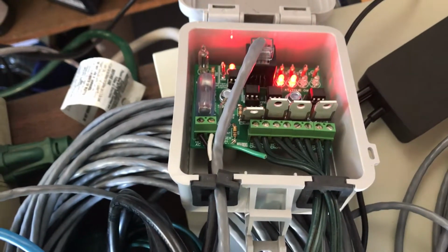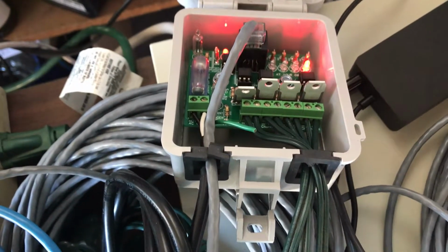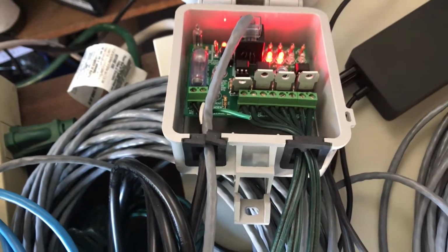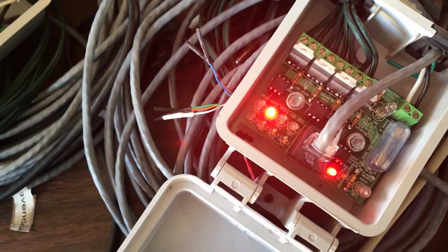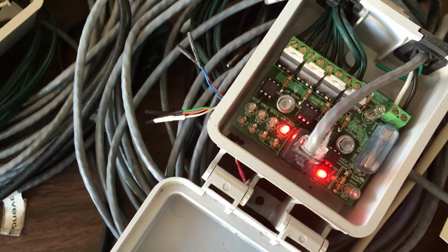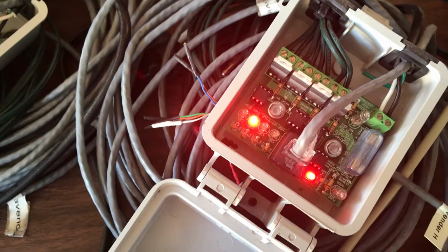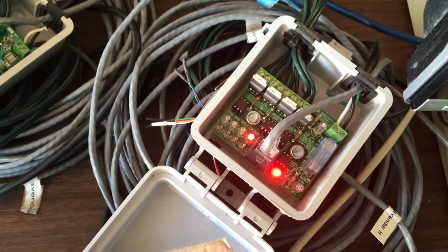These ones I don't have the AC power actually going to them, but you could see that the Pi is sending the commands. I'm going to hook up my lights later and get a visual test of the lights, but this is telling me that it's working. The Pi is interfacing with the solid state relays. It's sending out the commands to turn the lights on and off.